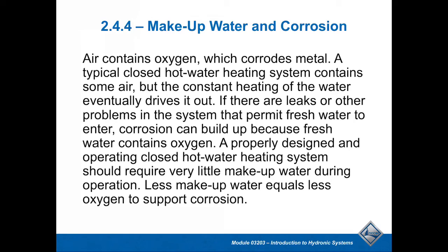Makeup water and corrosion. Earlier on in the first lecture, I had talked about how the makeup water system, as you bring in enough water, has a lot of dissolved oxygen in the water, and that's a challenge because we have to be able to get rid of that. On a system where you've got ferrous metals, one of your concerns is that the oxygen or the air in that water will create problems for you, or it'll rust out or corrode some of your heat exchangers and things like that. So you have to be a little bit careful on that.